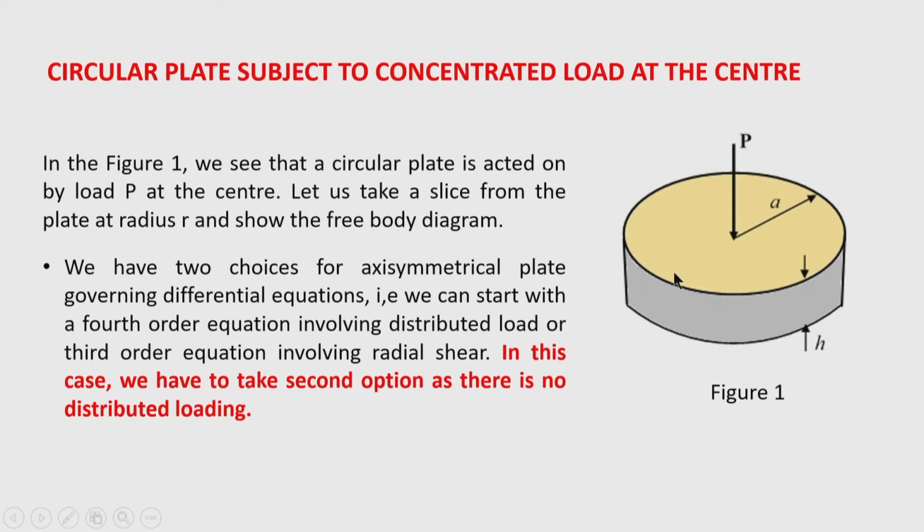Now, we solve such a problem by taking the differential equation of equilibrium that we developed for the axisymmetrical plate, and we can adopt either of two equations. One equation relates the fourth derivative of deflection to the distributed load, and the second relates the shear force to the externally applied load.